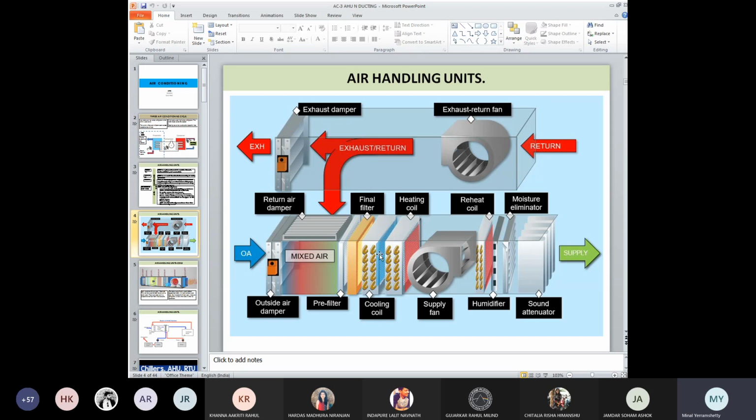And why the circulation? Again, because you are providing more surface area over which this air gets passed, and then you have a supply fan. In this case they are utilizing this. I have seen systems where they only utilize one fan. So then they have a supply fan, and then it is passed over the humidifier. Now, it can be of both types: a dehumidifier or a humidifier, depending on which climate you are designing your AC for.